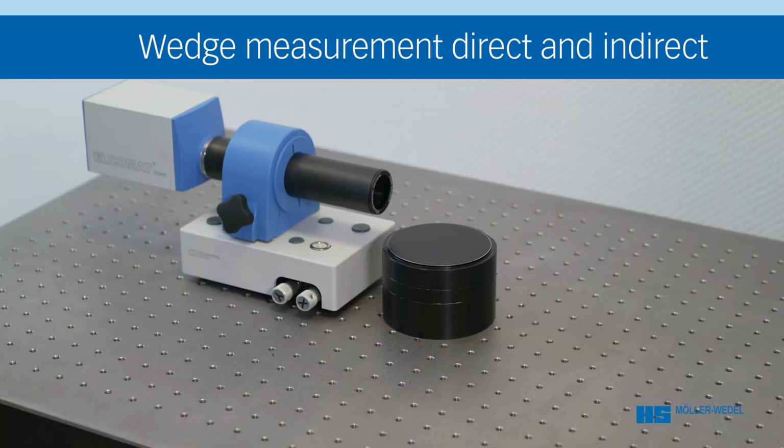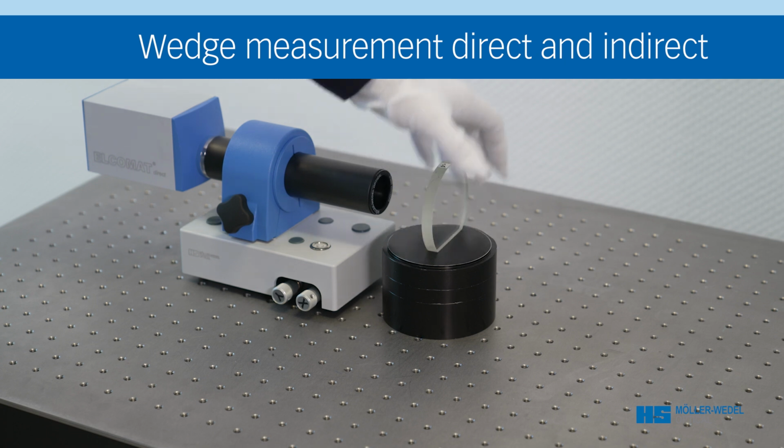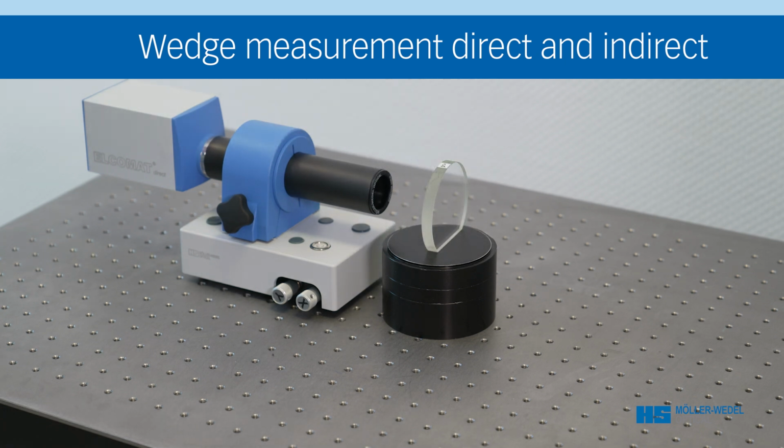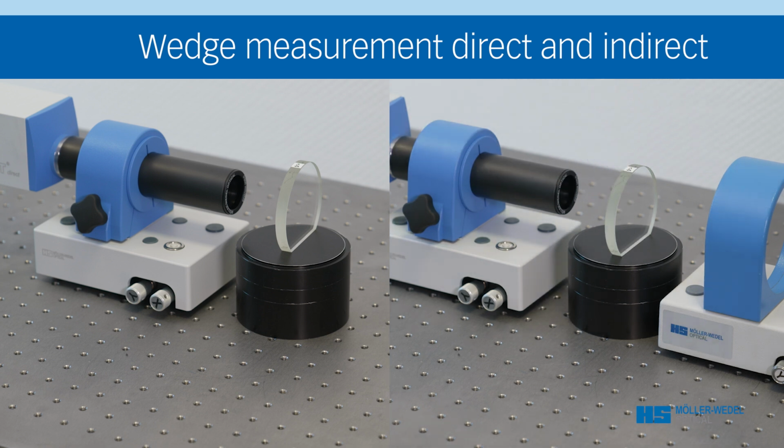The direct wedge angle measurement method is more accurate. However, if the wedge angle is too small, it cannot be measured because the two measurement signals cannot be separated below a certain angle difference. The size of this minimum measurable angle difference depends directly on the focal length of the autocollimator. The indirect method, on the other hand, can measure very small angular differences but is not quite as accurate.